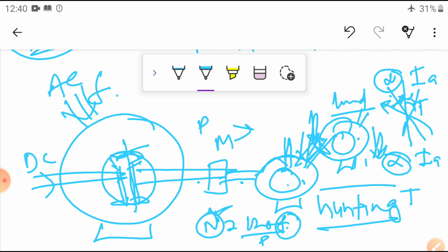It may occur at any time. Frequency changes may take place at any time, and the load may change suddenly, for example a coupling belt suddenly breaks, or suddenly some load is added. The rotor retards and accelerates, so there is a possibility of hunting being created.